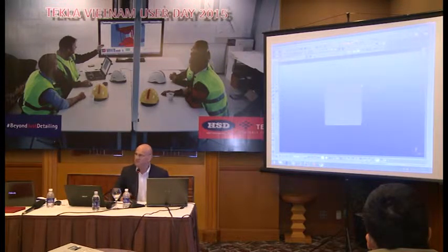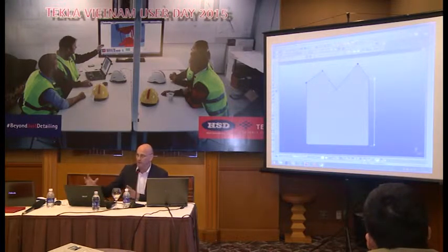Now if you click on that plate, it's the same as before. If you do a Control D and then click on the plate, you then get the edges. So then you can drag these edges to be another size, like so. Or you can pick up edges and move it so you can reshape this plate to be any shape that you wish by dragging it. That's direct manipulation. All of the system is moving more towards that way of working.